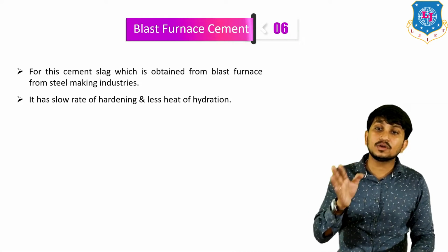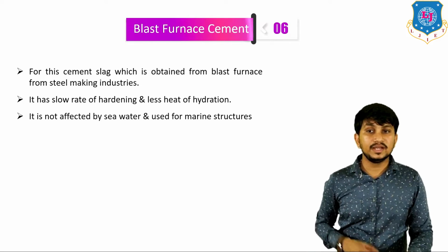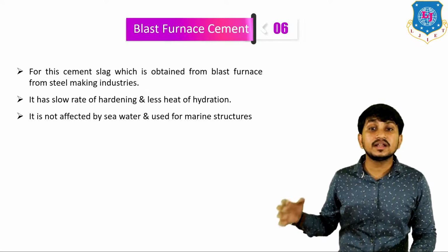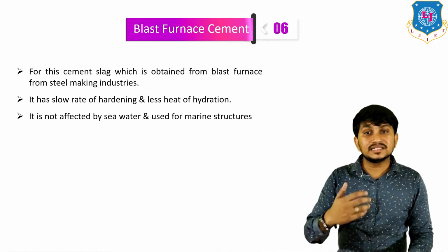It has slow rate of hardening and less heat of hydration compared to OPC. It is not affected by seawater and can be used for marine structures near the sea.